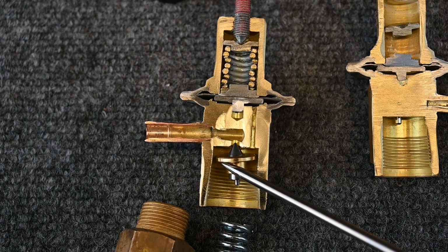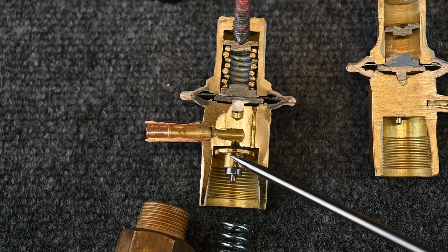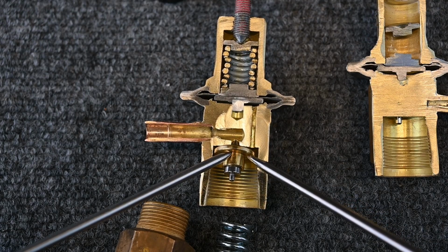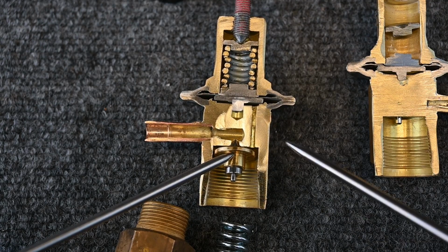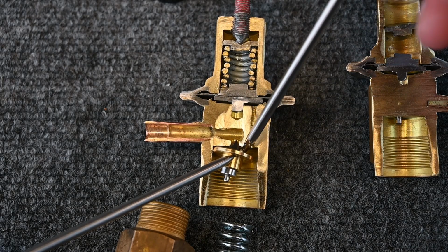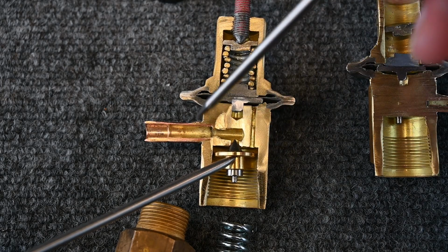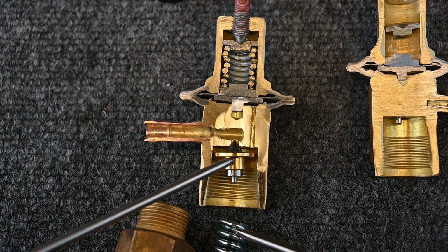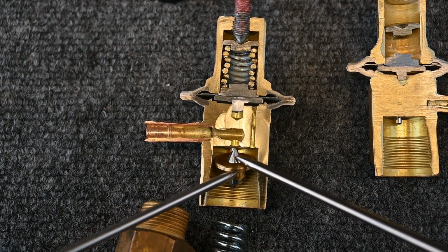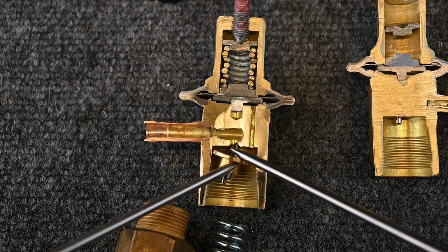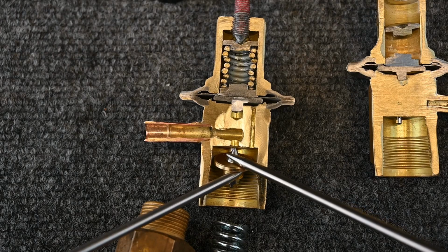What we do is we shove this cone up into that hole, and it changes the size of that hole. Notice it has this ring around here. That's where the spring pressure pushes up on the bottom side. And notice the gap here, and then again on the other side here. So as the refrigerant's coming down, it goes around this plate and it continues on. So this is by design, this ring around here. So this spring pushes against that ring. Now this cone shape is what's moving into and out of that hole, so it changes the size, controlling the flow of refrigerant.